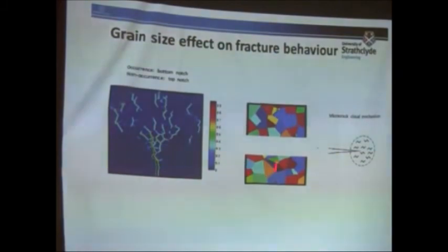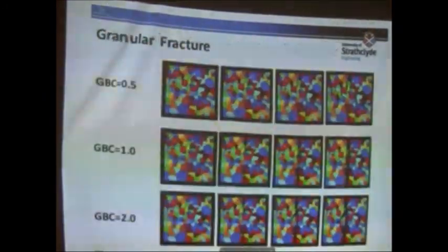But if it is inside the bulk grain, unfortunately it doesn't propagate. And then later on, once you apply your loading, a crack can occur somewhere here, and it can actually stop your initial crack. That is something known as the macro crack shielding mechanism. And this is something that we were able to capture by using peridynamics.